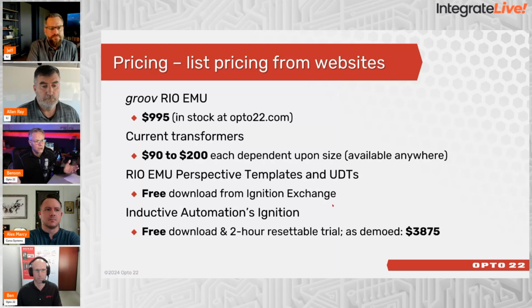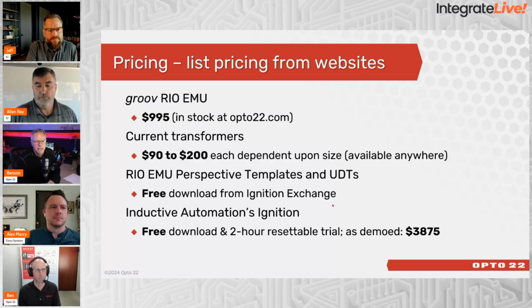Now, some loads need that. They need what's called reactive power to actually operate. But indeed, if you can improve your power factor, you're using your energy more efficiently, and therefore you're using the energy that you're paying for more efficiently.